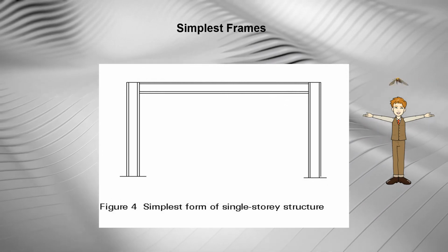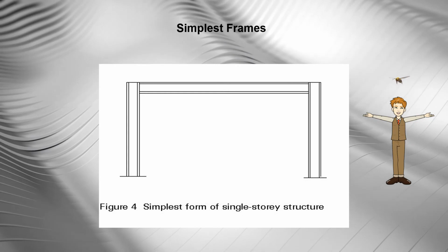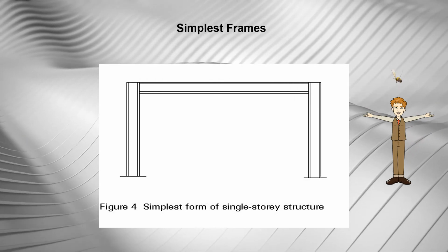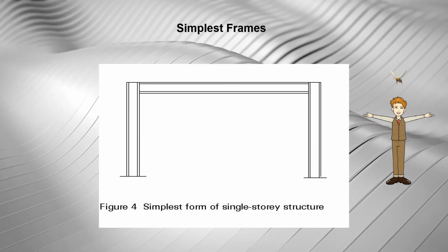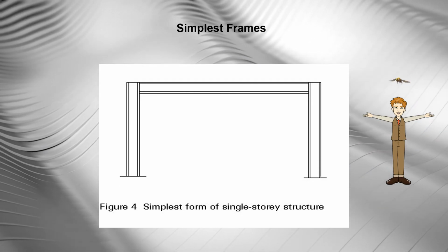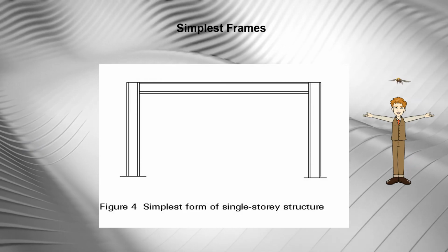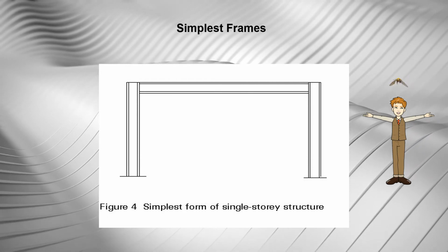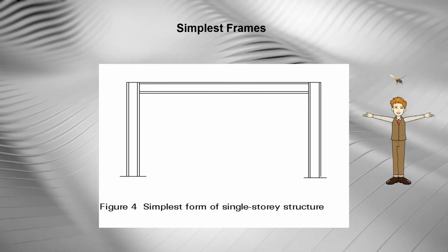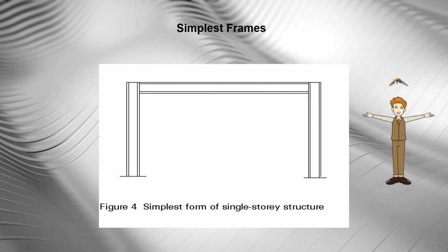In its simplest form, the crossbeam is designed as spanning between columns. The crossbeam acts in bending due to the applied gravity loads, the compression flange being restrained either by purlins, which support the roof sheets, or by a proprietary roof deck, which may span between the main frames and which must be adequately fastened.